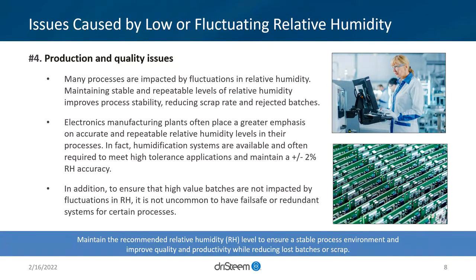I've seen as well, depending on good dry bulb control, 2.5 to 3%. And going the other direction, certain instances require plus or minus 1%. Since this is such a high criticality, I do have another slide on redundancy for certain processes. So if that's a redundant humidifier, for example, just so we have that control, I'll talk about that in a few slides.